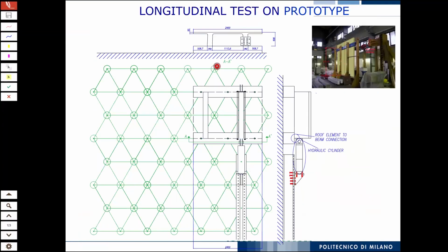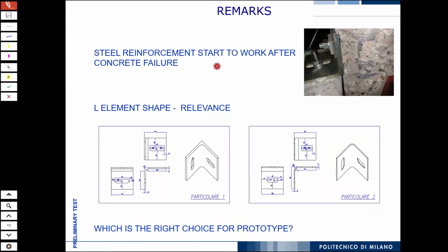And this means that these elements here can work like fuselage elements in the structure. So if you expect some earthquake, the damage is there, then you can put under temporary safety your structure. You remove those connections, replace these elements, but the elements around are sound.